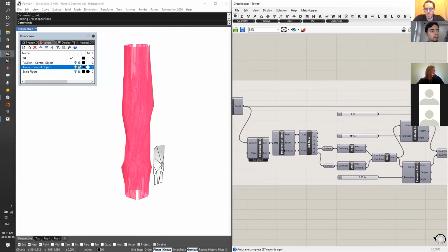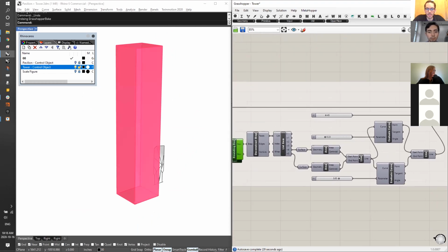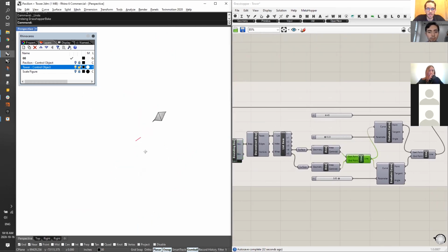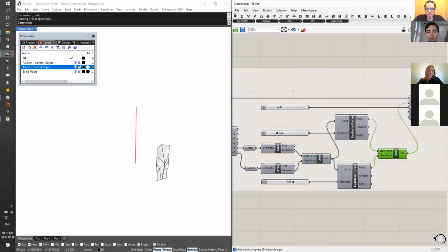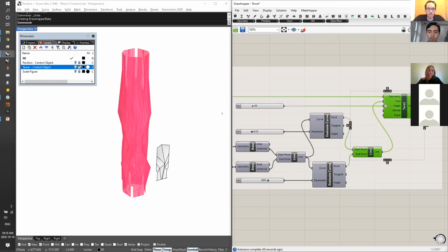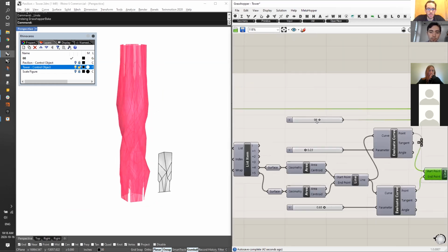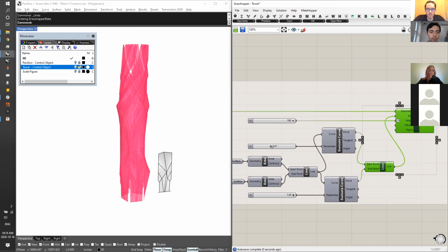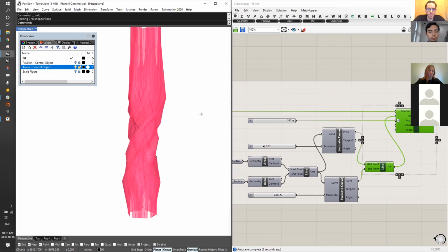And the way that's operating is we're basically taking a bounding box, taking a sort of the center axis of the entire tower, and then we're shrinking it down to a certain region, as you can see, because the way we shrink it can let us alter only a portion of the structure of the overall, right? If I were to change this to be, 0 to 1, it's basically going to just twist the entire thing. If I change this more so, you start to see the effect kind of traveling across the overall. Or we can sort of fine tune it to a very specific location, right at the center, right? If we do something like 0.2366.